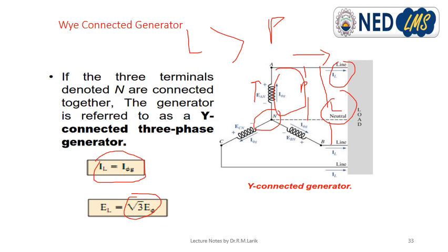In terms of auto transformers, we actually prefer the star connection, and the big advantage of a star connection is the neutral point. Actually, we need neutral at the distribution side, as I've talked about earlier, to drive the single phase load, which is line and neutral. So the biggest advantage of star connection is the neutral.